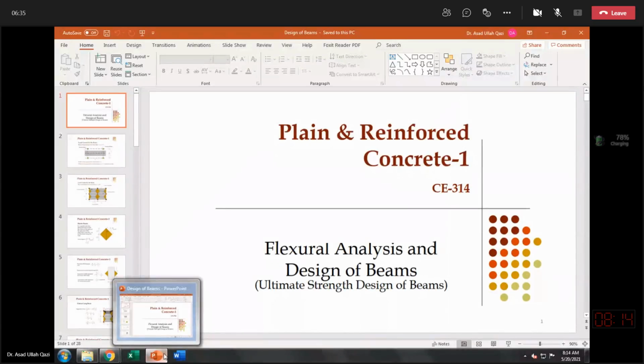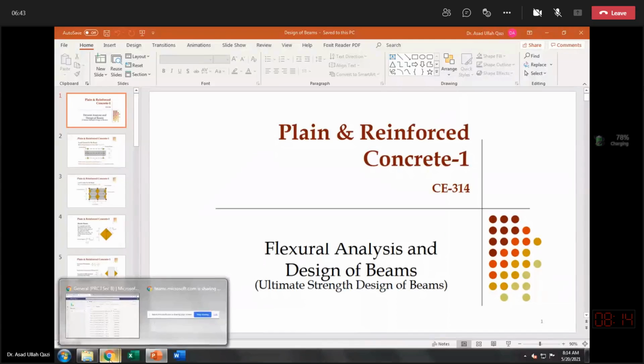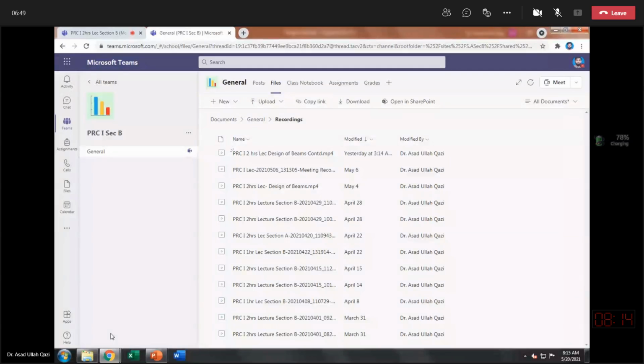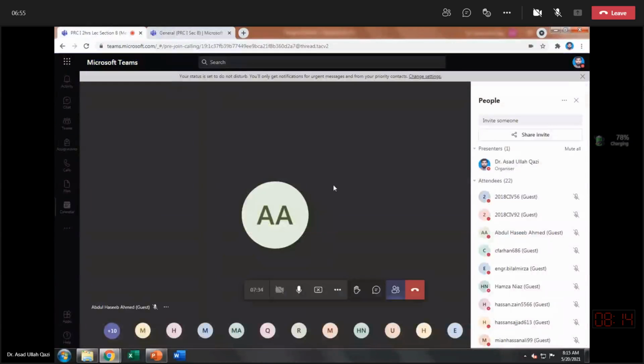So how much load will travel from the slab to the beam, and then after getting uniformly distributed load on the beam, the design as you are familiar with, direct design by calculating rho of tension control under reinforced beam and then designing it accordingly will be repeated.